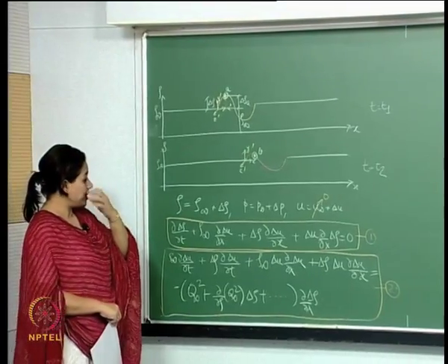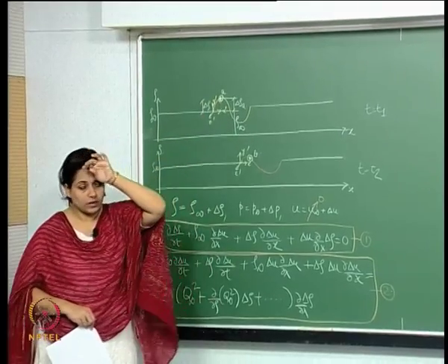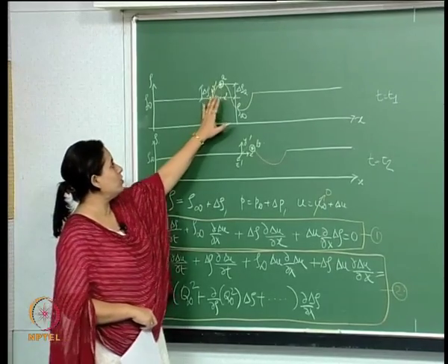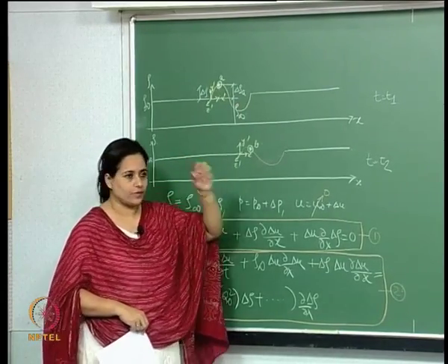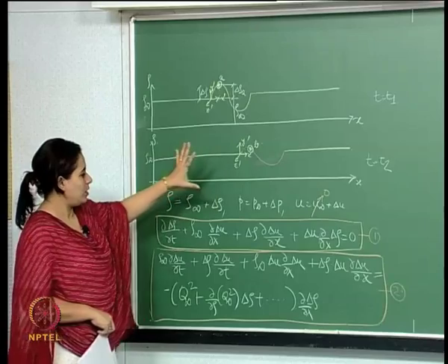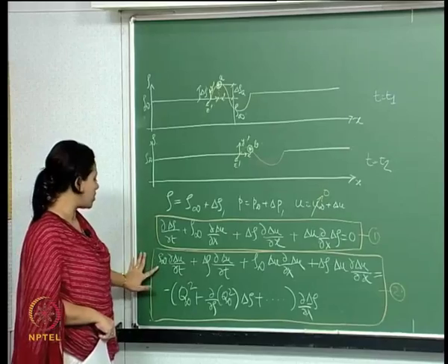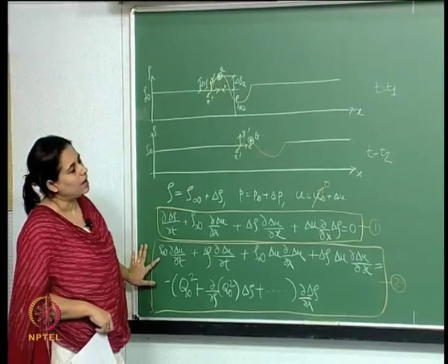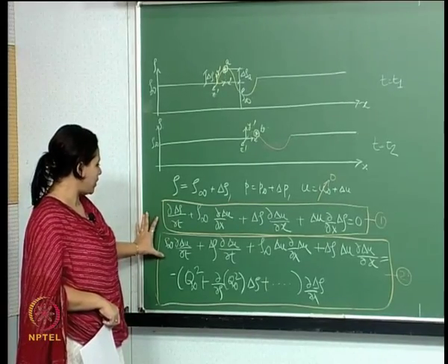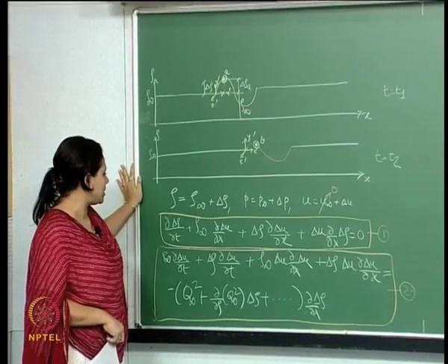We said finite waves. What are finite waves? When this perturbation is finite. It is not very small, or it is not something that you will ignore. So, you do have a finite perturbation, so you have a finite wave. For this picture, the governing equations are basically this. This is the continuity, and this is a combination of the momentum and the energy equation. Now this seems to be too complicated, so let us do one thing.